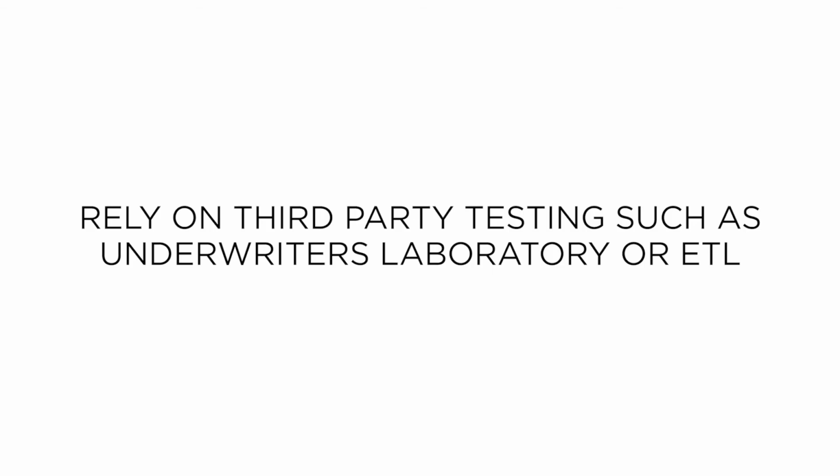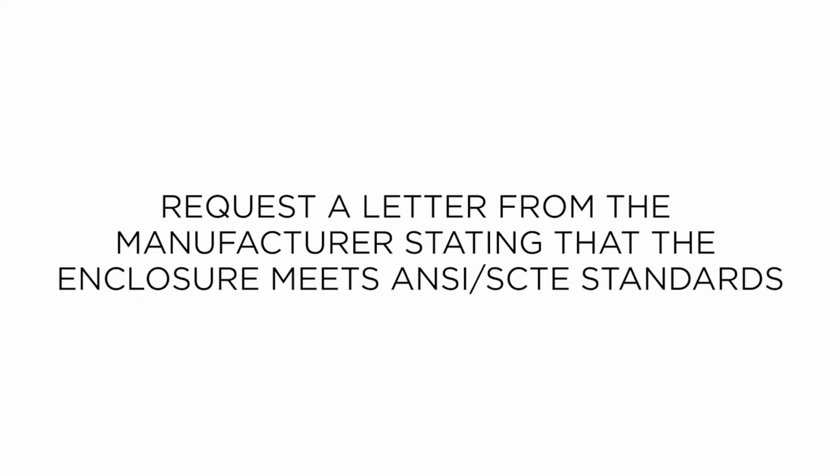ANSI-SCTE testing is essential for all underground enclosures. How can you tell if your enclosure has been tier tested? Rely on testing conducted by a third-party organization such as Underwriters Laboratory or ETL. Request a letter from the manufacturer stating that the enclosure meets the published ANSI-SCTE testing criteria.